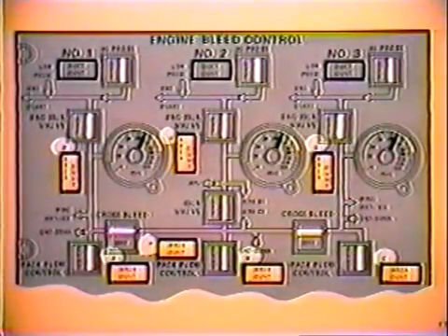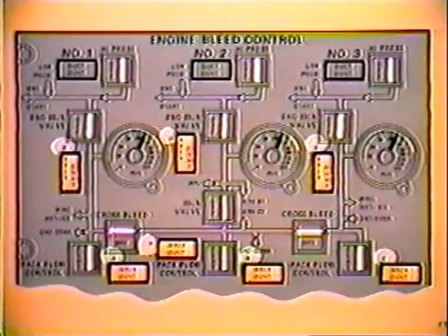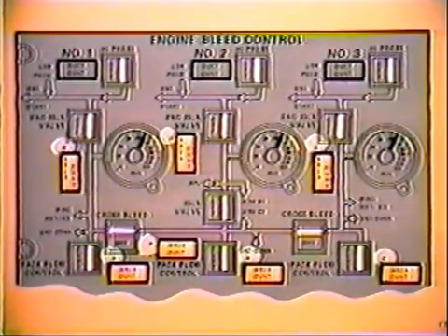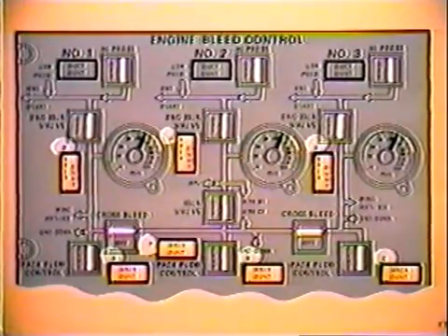The ducting to the wing anti-ice system from the pylons outboard is also monitored by the area overheat detection system. The anti-ice duct fail lights located on the overhead switch panel, identified as F and G, monitor this ducting. These letters are intended as an aid in choosing the proper procedure to be followed and for proper identification of the affected area for maintenance use later.